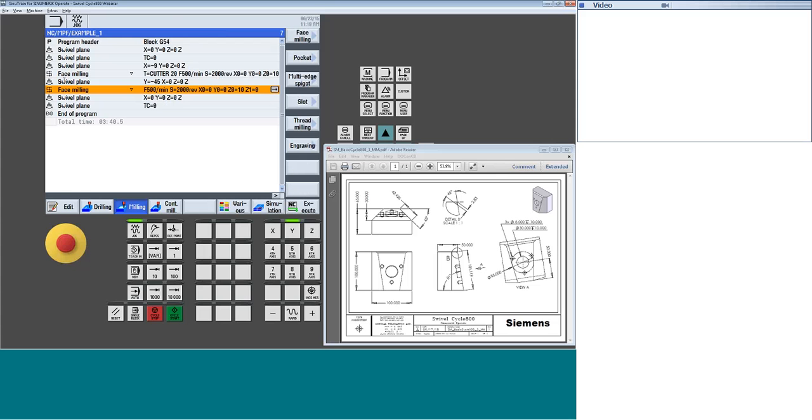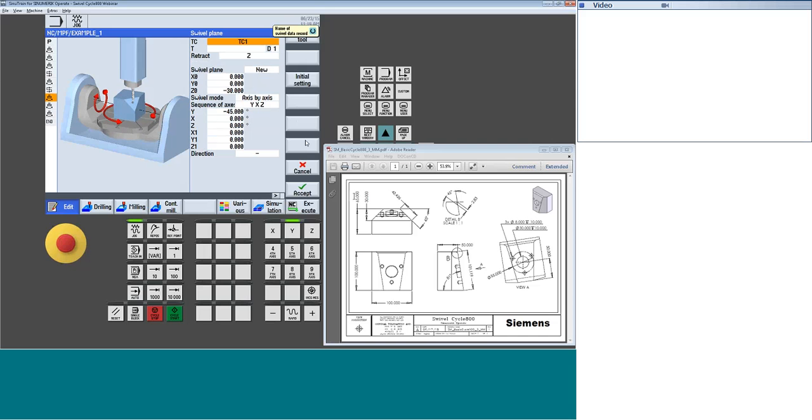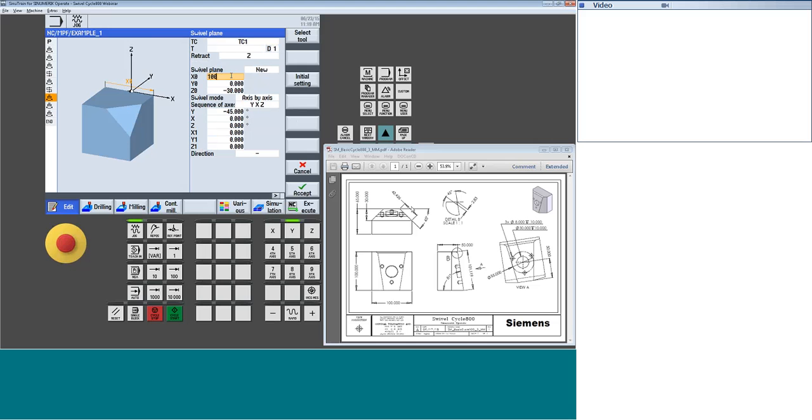Now we jump back to swivel cycle. You can either go back or you can certainly cut, copy, paste like we do in any other program. So I could paste this down. In this case, I want to shoot my 0 over to the far corner. So I'm going to move my 0 over 100 mil. And then I want to drop down to this lower corner. If I knew where this position was, which I don't, but if I had that dimension, I could have moved to that point and then done a rotation. And then all my stock would have been in the plus direction.